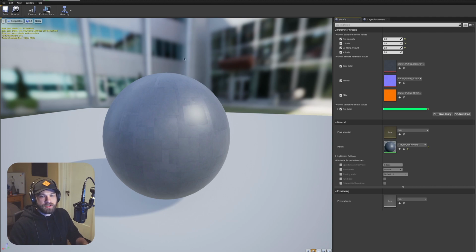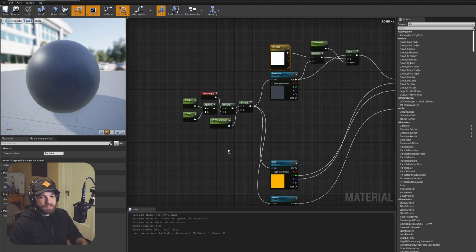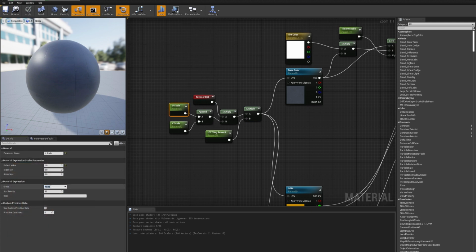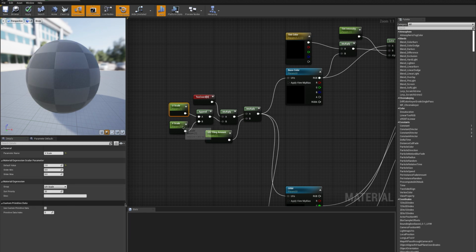So one more thing I'm actually going to show you guys, just for a little bit further housekeeping, right? You can see it's kind of strange that tint intensity is up here and the color's down here, and it gets mixed in with some of the UV scaling parameters. We want to make sure that we keep things clean so that they're easy to find and change, and everything's next to each other. So I'm actually going to go through all the different parameter sections here, and I'm going to apply a group. So I'm just going to call this one UV scaling.